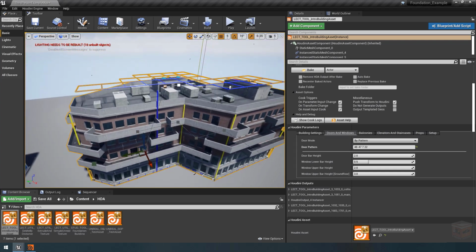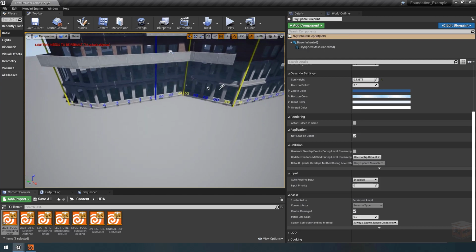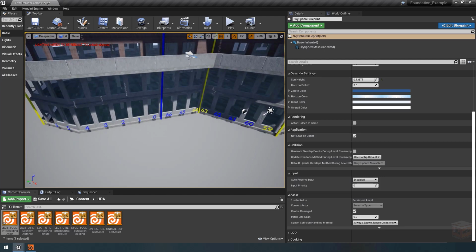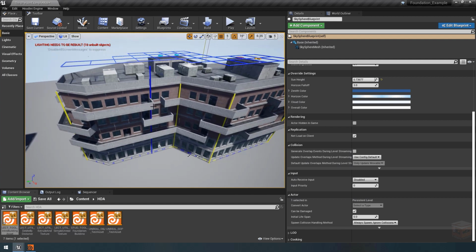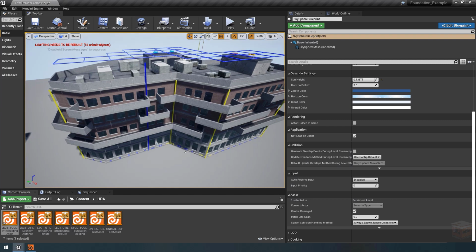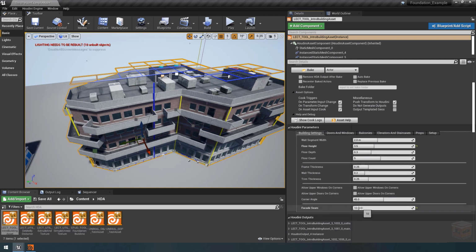And then last, we have the seam in the building. And the seam is where our tiles, as the numbering goes around the building, as you can see here, jumps up one floor and then continues on. And when it comes to the balconies, this is quite important, because later on when we build the balconies, they can go into different patterns as they go up the building, and controlling where the seam is will allow us to better control how the balconies switch as they go up the building, where they're basically cut. So we will also add the ability to move the seam in this lecture as well.